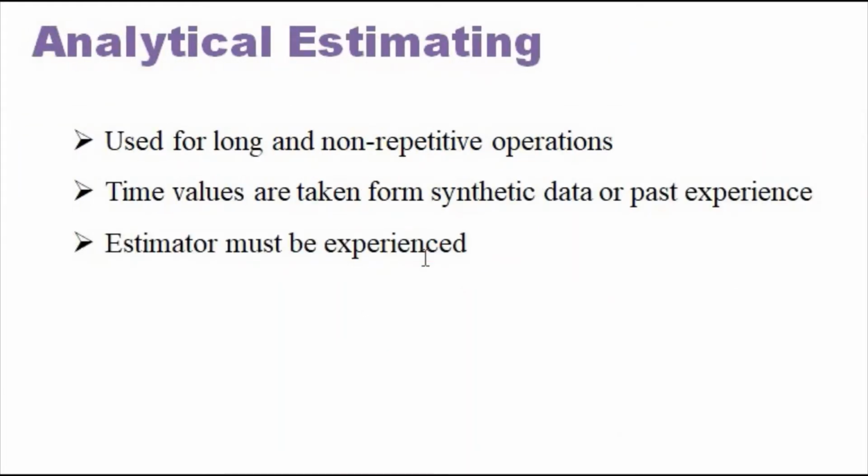Now, generally, setting the time standards for long and non-repetitive operations by the stopwatch method is quite difficult, and it is uneconomical also when there are long and non-repetitive operations or non-repetitive type jobs. Now in such cases the stopwatch type methods are not good to follow. Then in this case, synthesis method or analytical estimating is followed instead of following the regular methods.